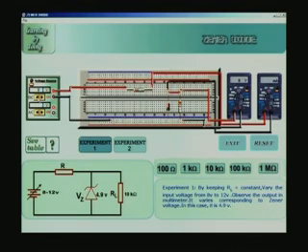Now let me quickly switch on the power supply. First let me choose the experiment and then I will switch on the power supply. So now I have switched on the voltmeter, everything. There is 8 volts applied at the input, this resistance is about 120 ohms, the Zener is about 4.9 volts, and I have connected a load of 250 ohms, you can see.